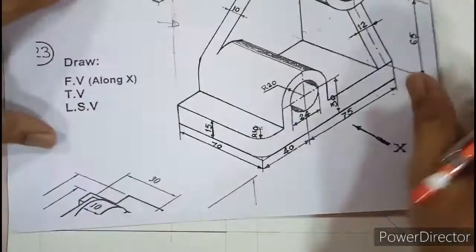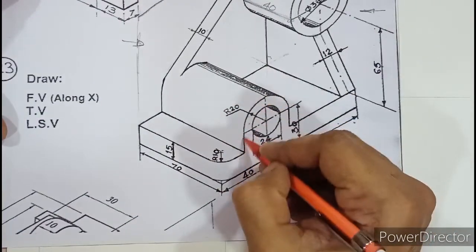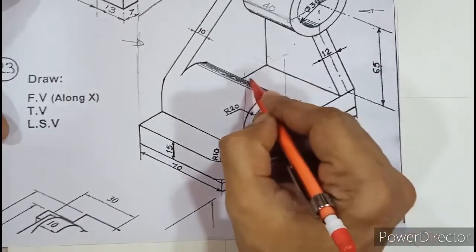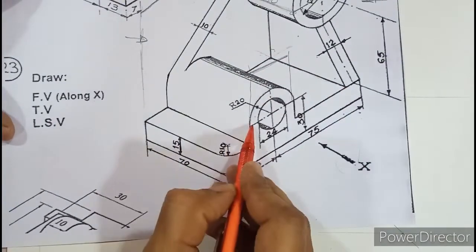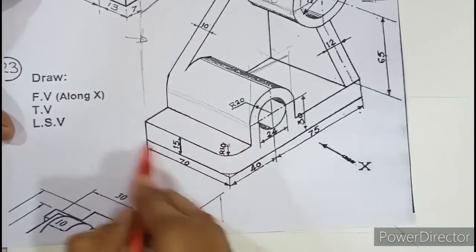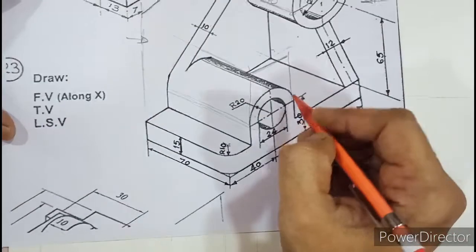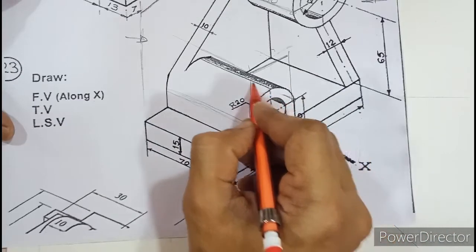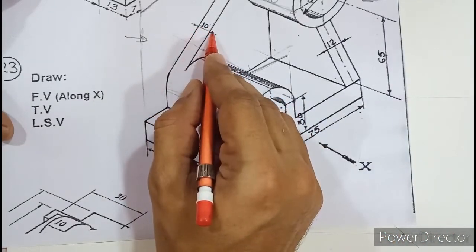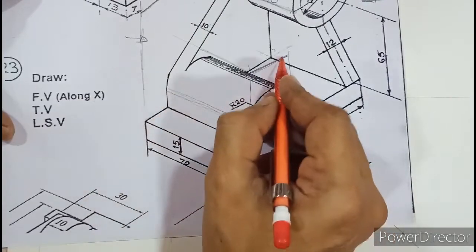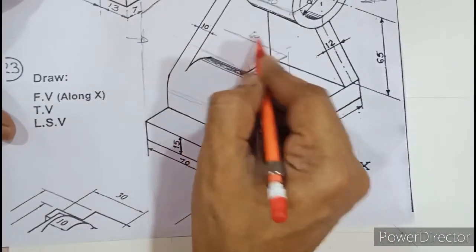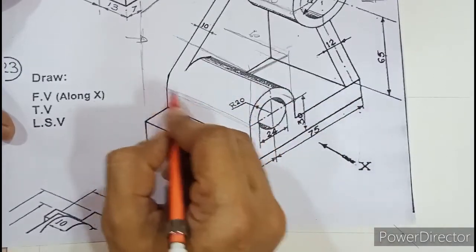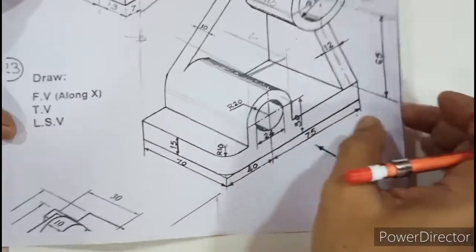So similarly, move on to the next part of the cylinder. So now all of you will focus on this cylinder. So in the top view, this circular edge, if you project, will be seen as a straight line, isn't it? Then this boundary is seen fully till 70 millimeter. Okay, this one is 70. But if you look from the other side boundary, that is not till 70 because there is a plate 10 mm thick. So if this is 70, that will be 60. So you can see three lines of unequal length. So one will be 60. Then this is the circular edge seen as a straight line, and this edge will go up to the 70 mm boundary. So that is how the top view of the semi-cylinder looks like.